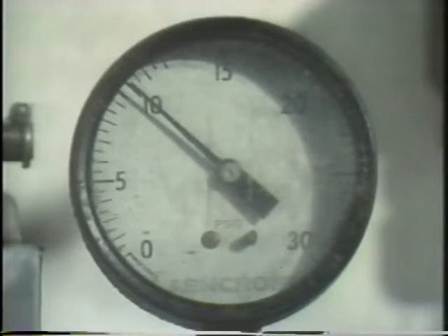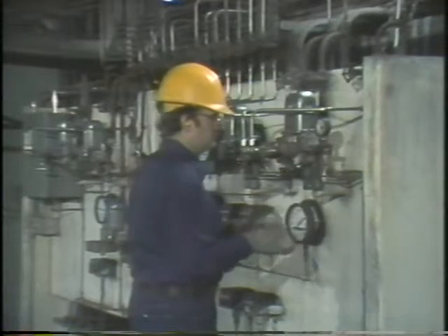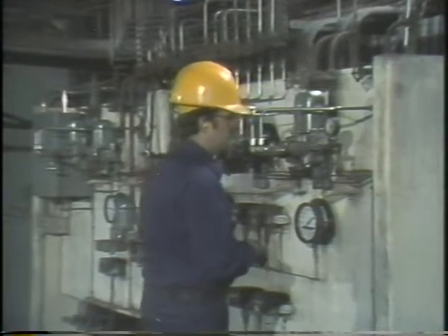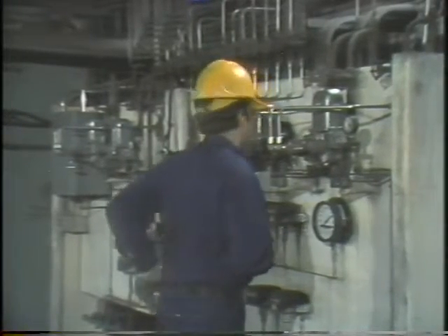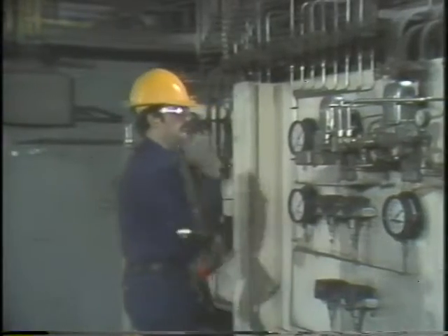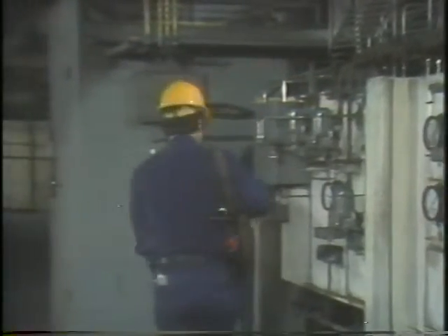10 psi. That's higher than it was before. I'll just check this connection here at the output tubing. Make sure there's no leak. I don't see any leaks in the process piping either. I'll check back with the operator, have him put this system back in automatic and see how it works.